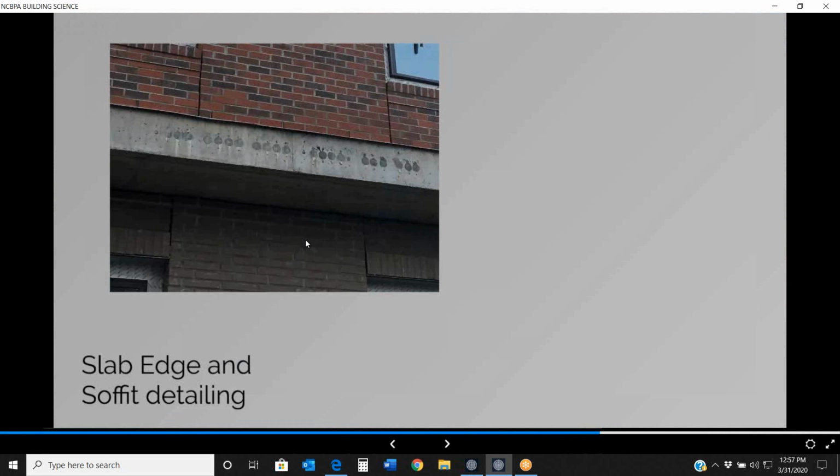We can't drill at certain locations more than 1 inch in fear of hitting a tendon or a cable. We have to go back and kind of grab back all these holes. And then what you'll see sometimes, as this photo will show, is we've got our PT heads, which are very delicate, just kind of out to the weather. They're gonna take full brunt of the weather, and we don't have any protection over them.